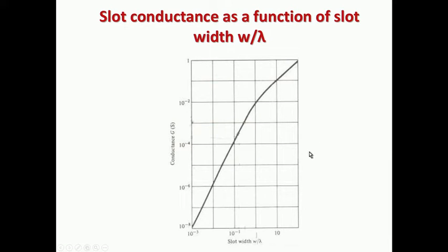But one thing should be remembered: in these cases the loss resistance and the radiation resistance are not exactly in series as we have seen for simple antennas, because here there is a nearby ground plane or a lossy ground plane.